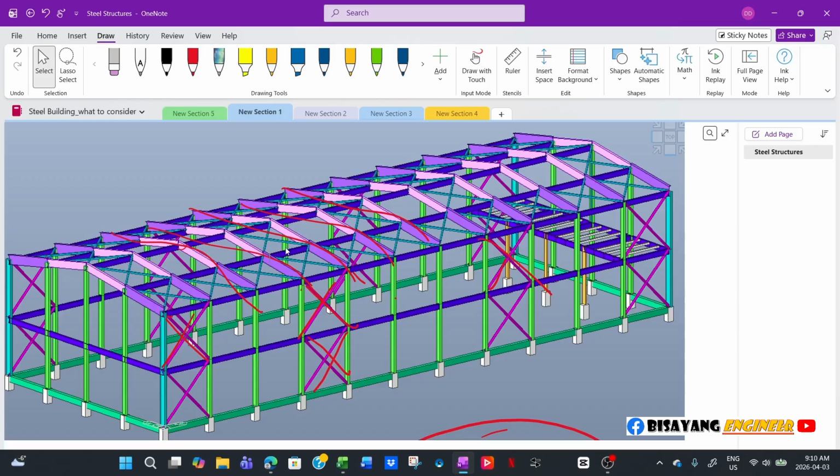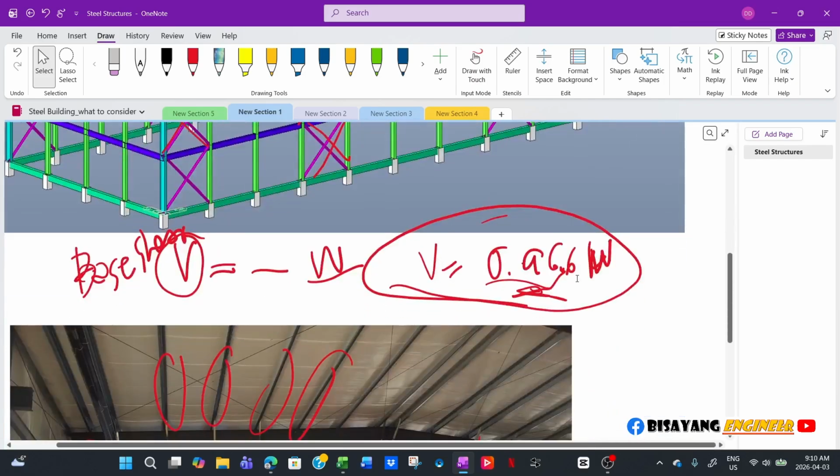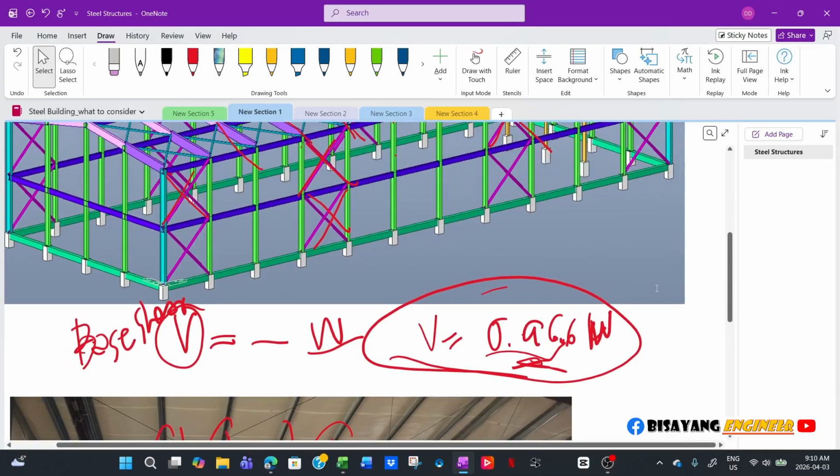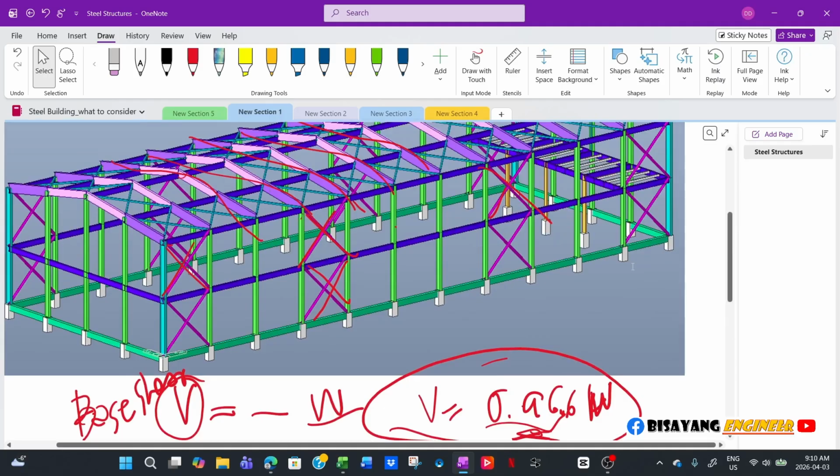So I told him, if it's just static equipment, just supporting gravity alone, then what you can do is have either a separate footing or a monolithic footing with this slab and just make it thicker, based on the requirements like bending and punching.